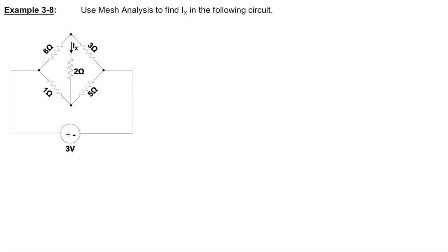Let's think about the fact that there are a lot of closed loops that we could draw around here that include the source. We could go this way. We could just go through the bottom here. Mesh analysis says that if a loop contains other meshes, then it's redundant and it's not a mesh. So for that particular circuit, there are 3 meshes.